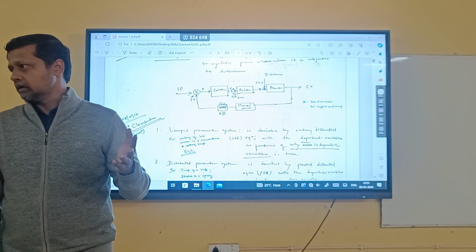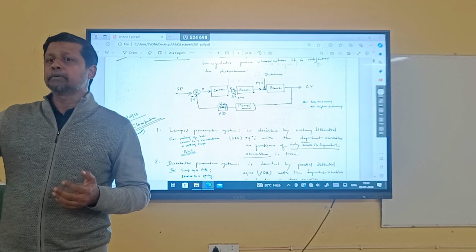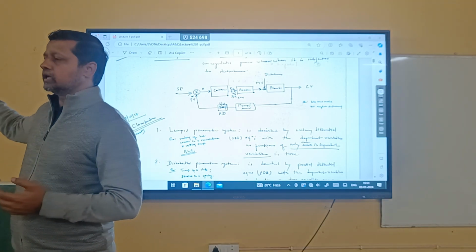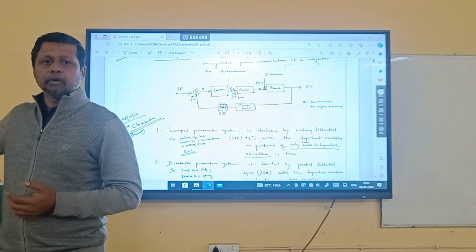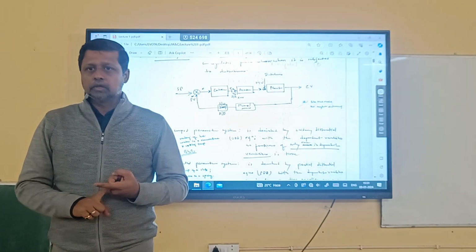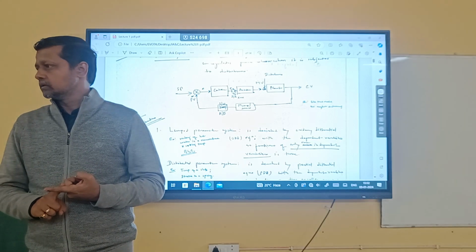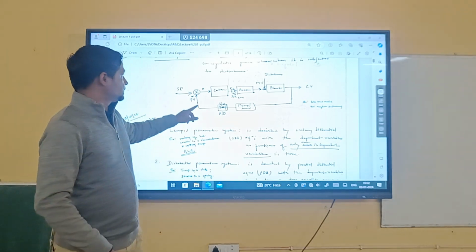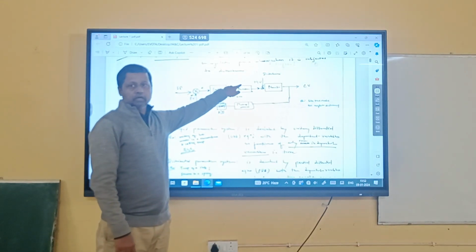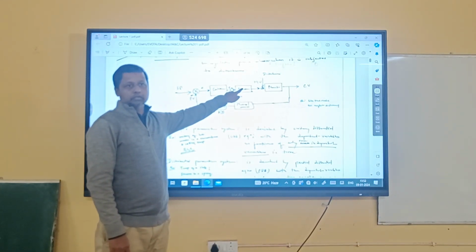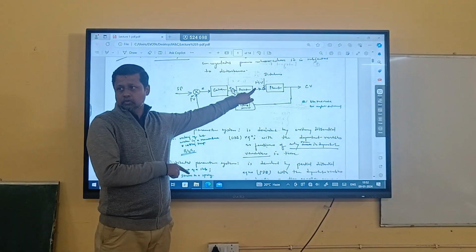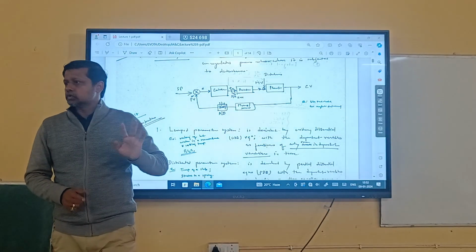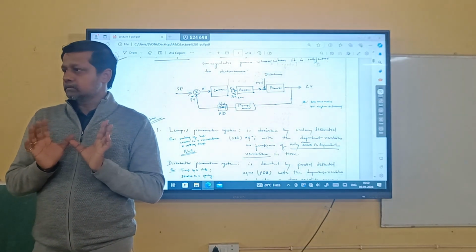Understand? Here, I want to continuously monitor the temperature profile, and that profile should be reflected on the HMI at my monitoring section. Clear? So is that continuous or discrete? That's continuous. But somewhere, now the controller has taken a decision. It is giving a command to the actuator. Based on that, if the actuator was earlier open, now it is closed. If it has to open, now it will. So can it be treated as a discrete signal?